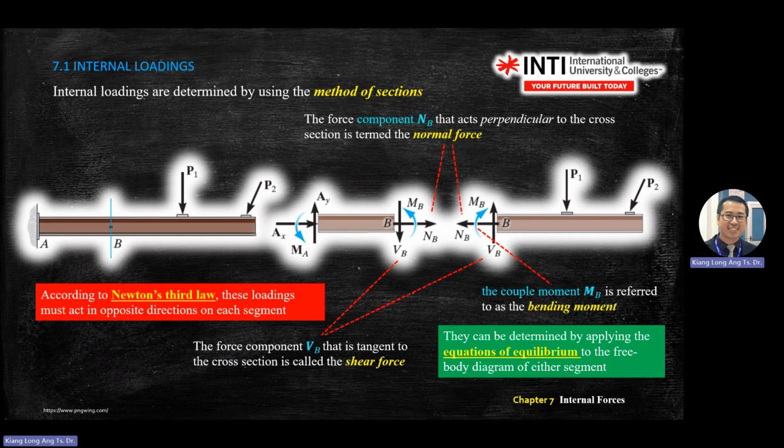That means for this one, all the forces equal 0, all the moments equal 0, for the left segment. If you still have unknowns, don't worry. You go to the other component, use all the forces equal 0, all the moments equal 0, and solve for this one. Then you compare left and right. There are some components that you can solve simultaneously.